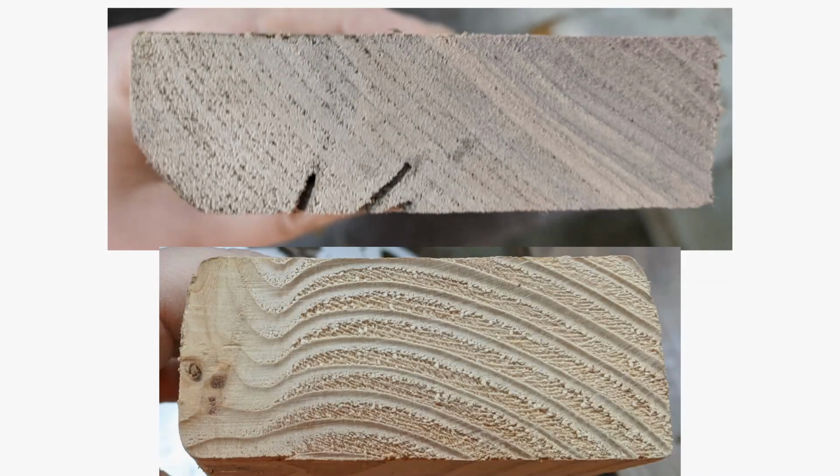Here I have two pieces of wood, cut perpendicular to the grain to reveal their grain structure. The straw-like characteristics of the wood can clearly be seen, all these little interior spaces, all these little straws that you can see in the microstructure. In terms of species, the wood at the top is black walnut, and the wood at the bottom is Douglas fir. And in terms of groups of wood, black walnut, like all walnut, is a hardwood species, and Douglas fir, like all fir wood, is a softwood species.